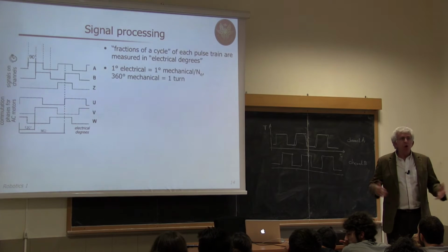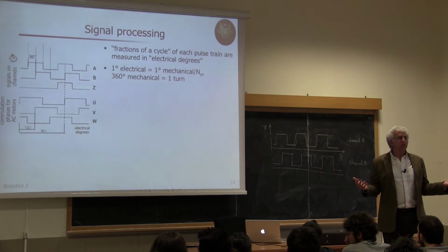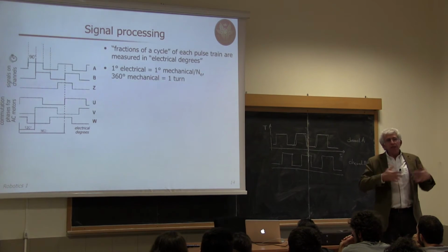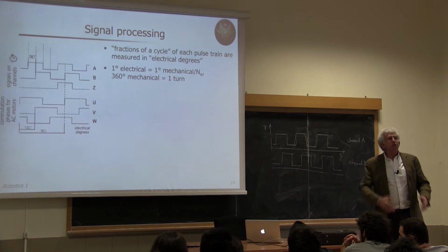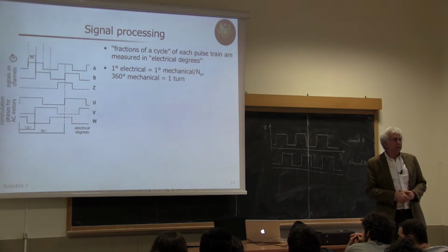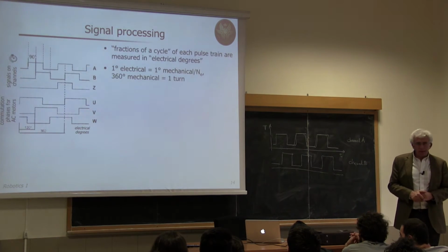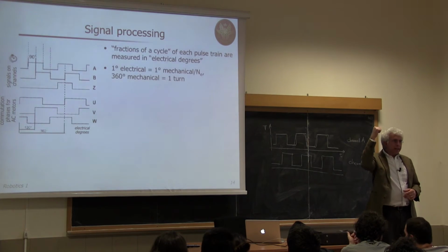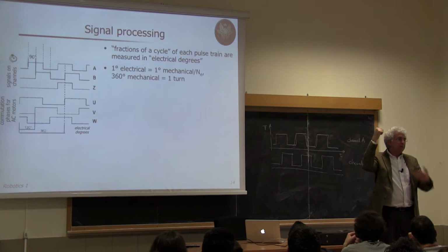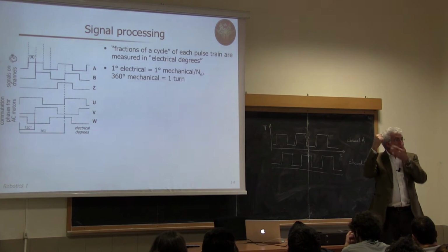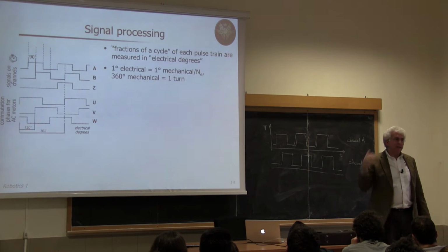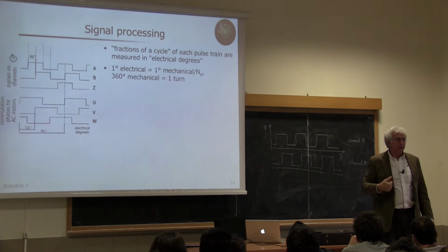So it has to find a reference configuration from which it starts counting incremental angle, okay? So you will see the robot moving one link at a time, so one joint at a time, typically from the last link, then back to the bottom, to the base.